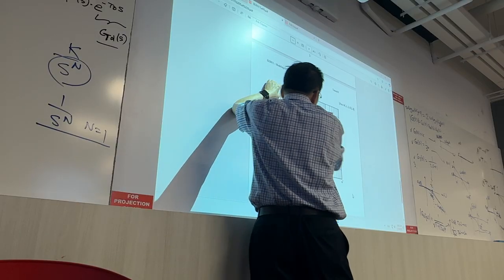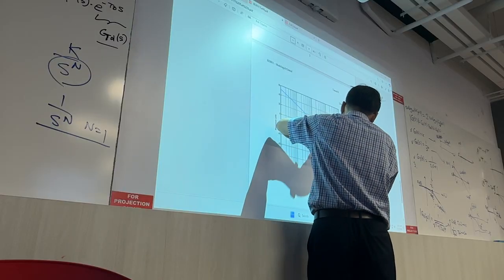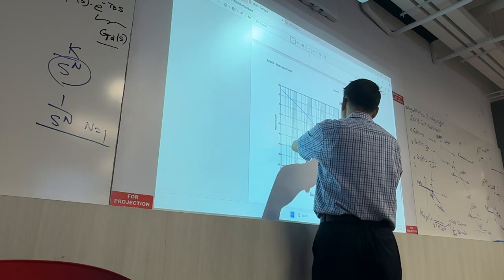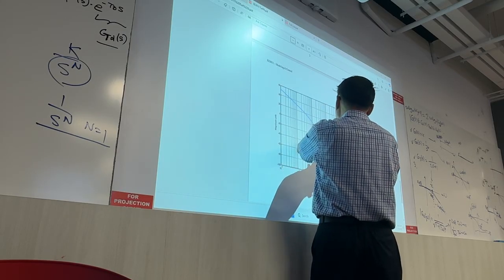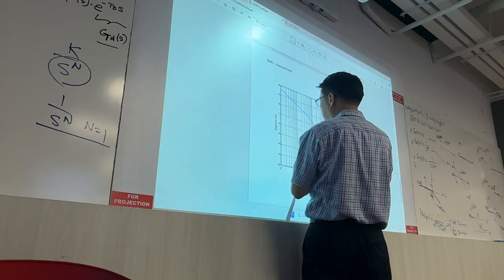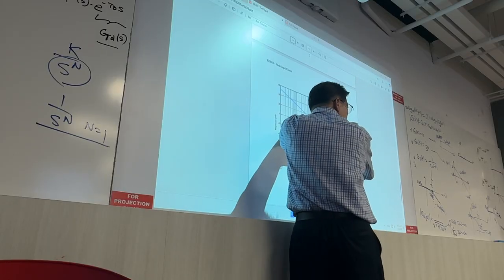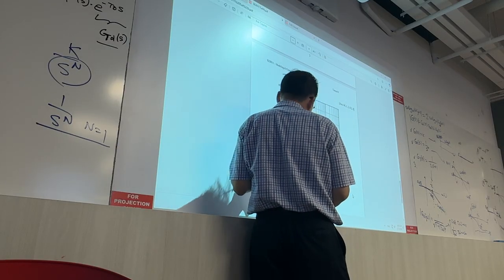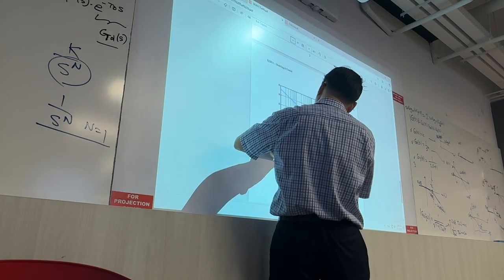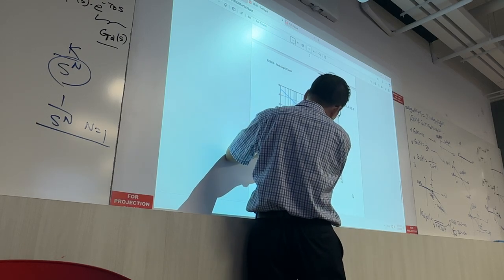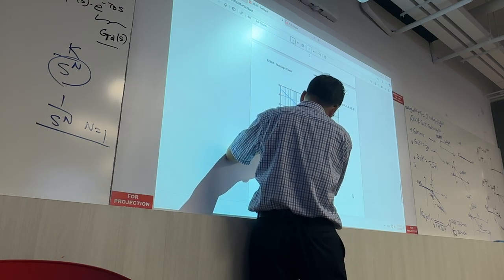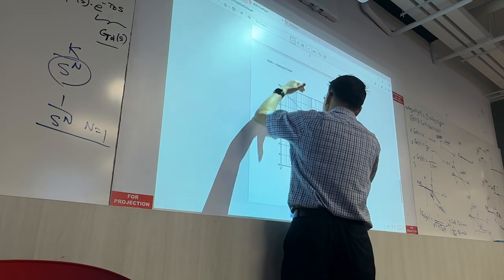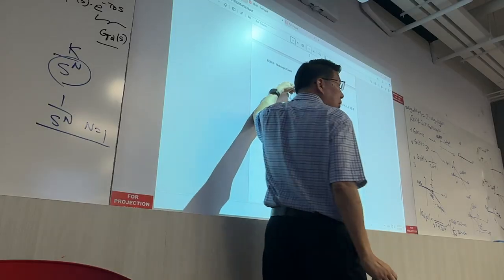Then on this side, in the last decade, here is minus 85 already, but here is about minus 20. So minus 20, minus 80, there is about 60. That's the change in 1 decade. So this is minus 60 dB per decade. You draw a line from this point to this point, and you shift it to fit in. So the left portion and the right portion, you have fit in already.